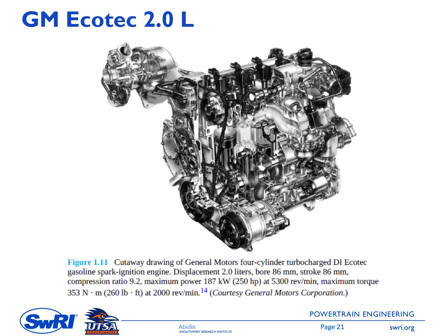So 4-cylinder inline means the cylinder axes for all cylinders are in the same plane. The bore is 86, the stroke is 86, so you can see here the bore equals the stroke. Sometimes it's called a square engine. Okay, and then the compression ratio is 9.2, and the maximum power is 187 kilowatts or 250 horsepower. And this is also the data for the maximum torque, and this is the speed at maximum torque.